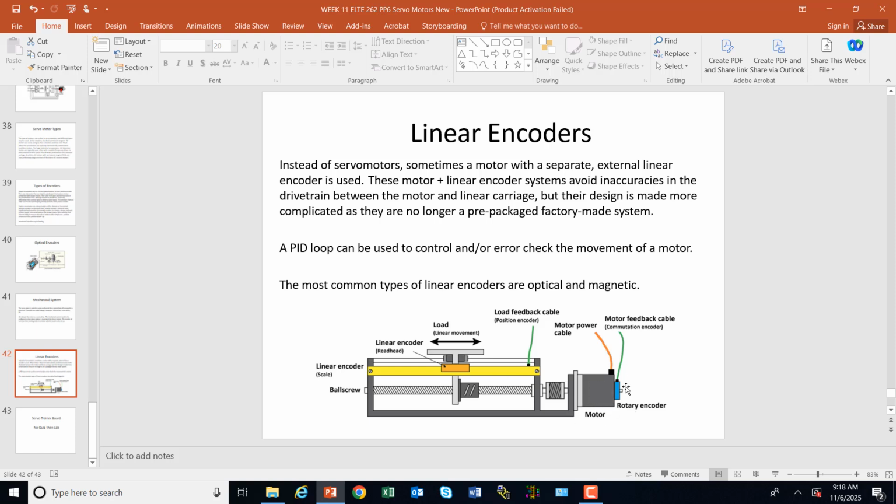This motor can be told to speed up, run really fast, then start slowing down, and then stop. Well, this linear encoder can measure that and see, yep, it's speeding up, it's going really fast right now, it's starting to slow down, it stopped. This linear encoder can send all that information back to the PLC to be sure that this motor is doing exactly what it wants.